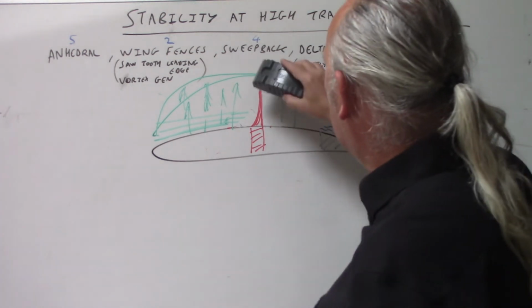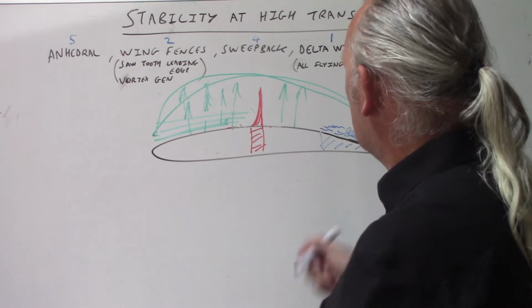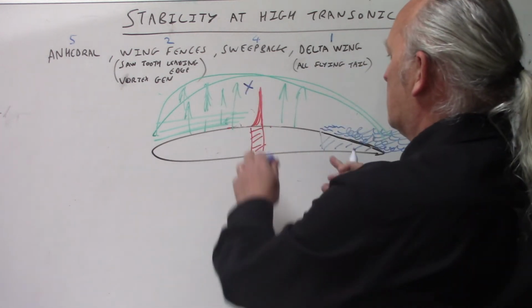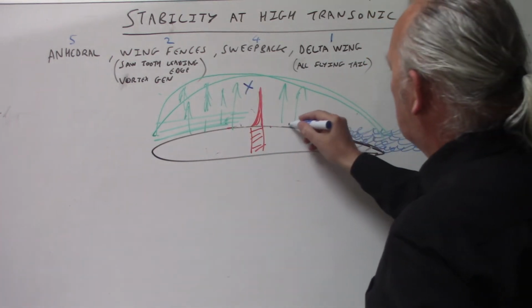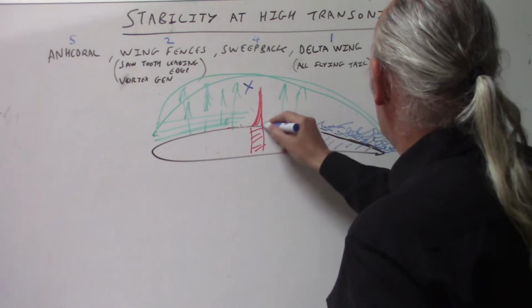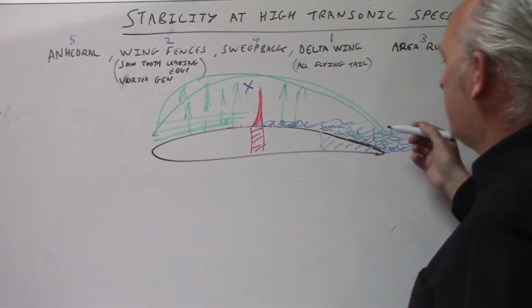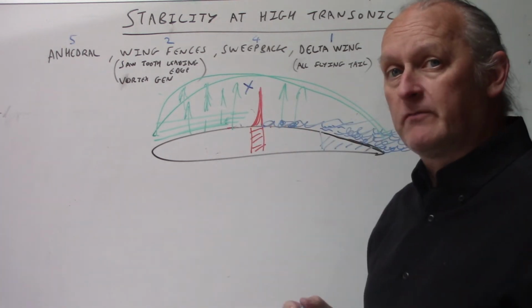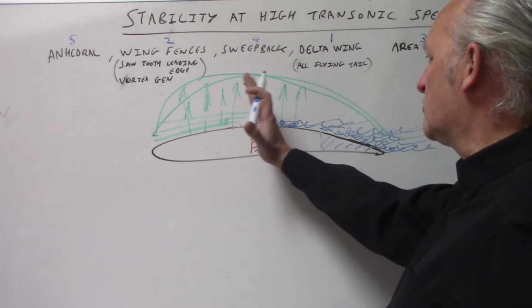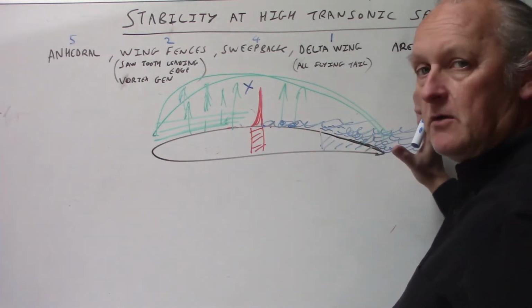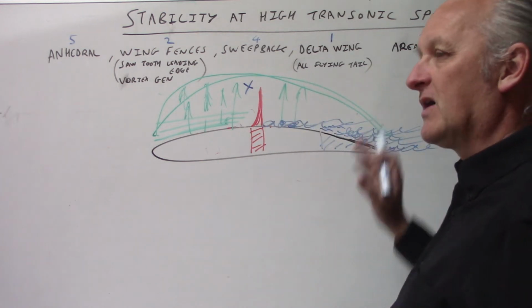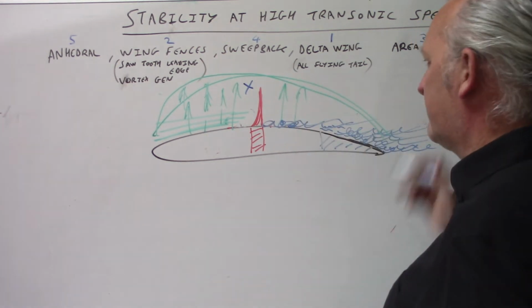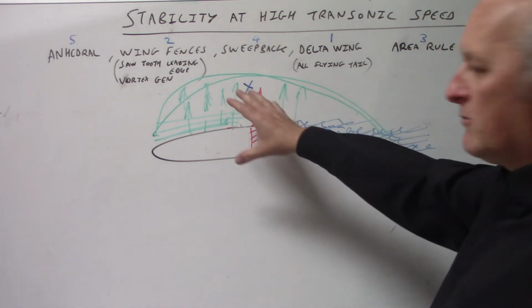Right, now, when you've got that, your centre of pressure, okay, might have been here. Now, your centre of pressure, because you've lost some lift at the back end, and in extreme variations you can have turbulent flow all the way to the back. The turbulent flow at the back will, as you go faster and faster, increase until it meets the shock wave. Okay, and then the shock wave kind of sweeps the wing and takes the turbulent flow back over. Right? So as the shock wave moves further back, as you go faster and faster, the shock wave will form further back on the wing until the shock wave forms at the trailing edge. So this is like about Mach 0.8.